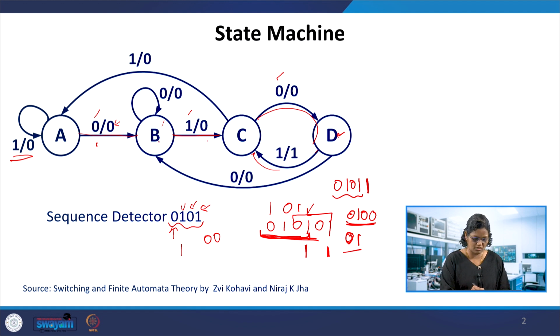So you stay in state B. Then at C, 01 is achieved, and you have to get 0 here, but instead of 0 you get 1. That's not going to form part of the expected sequence, so go back to A again, 011. This is the next breaking sequence.